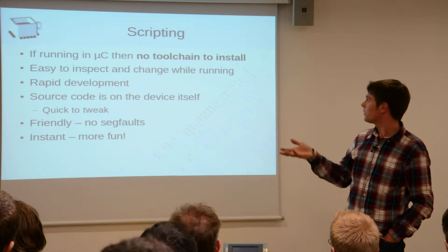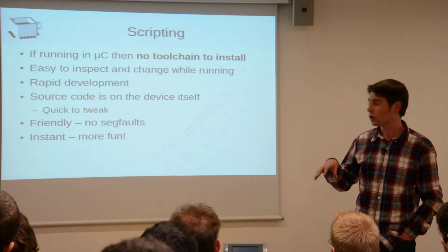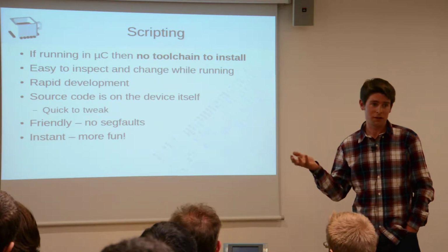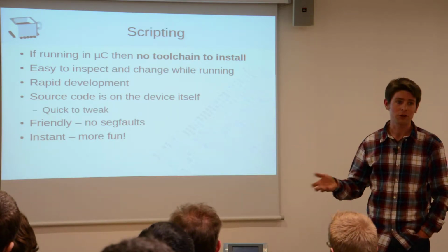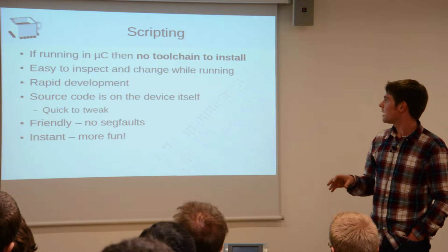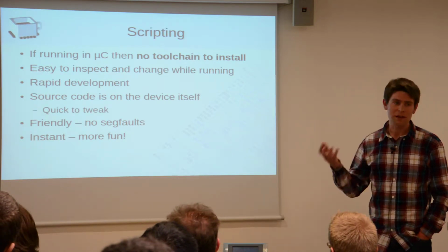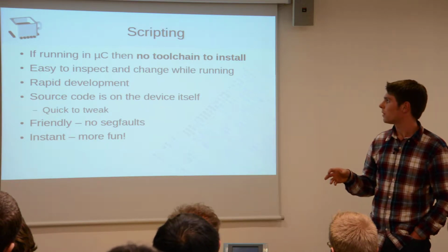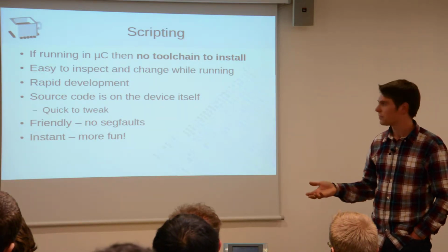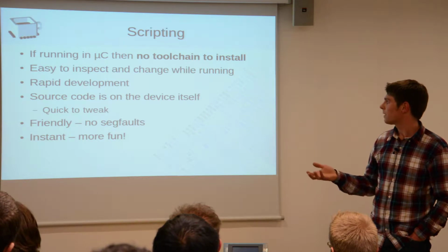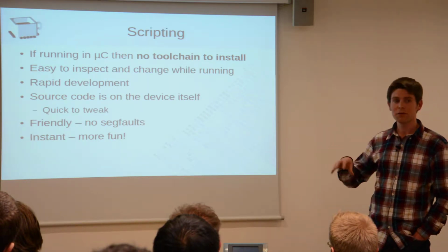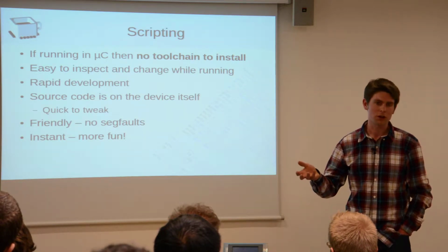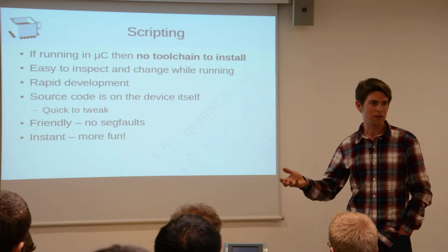So why would you want to run a scripting language on your microcontroller? Well, you can solve the toolchain problem: you just don't have a toolchain, because it's all in the microcontroller. It's obviously easy to inspect and to change, and that does a lot of the debugging for you. Obviously that makes development much, much quicker. And another really nice thing is having the source code on the device itself, not for production hardware, but more when you're doing stuff yourself.